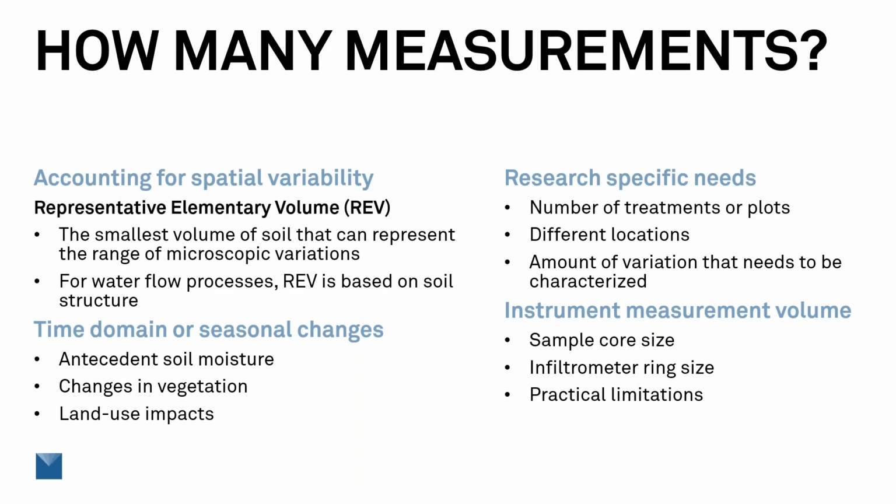So if we were to go out and till a field, from the point you till the field to later on in the season, you typically will see a continual decrease in the hydraulic conductivity, for example. As the soil settles, you're going to see those pores become more compacted, and you're going to see a change in the hydraulic properties. And then ultimately, you have to think about your research-specific needs.